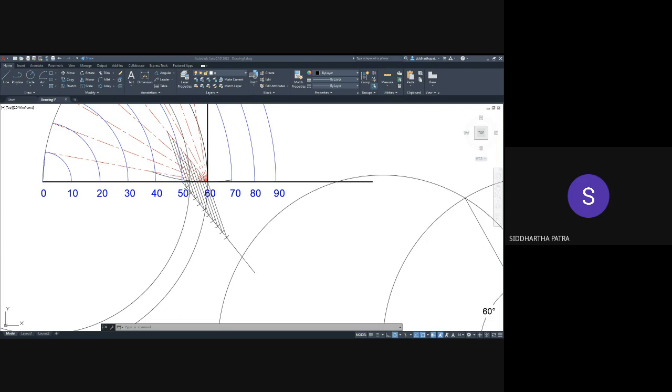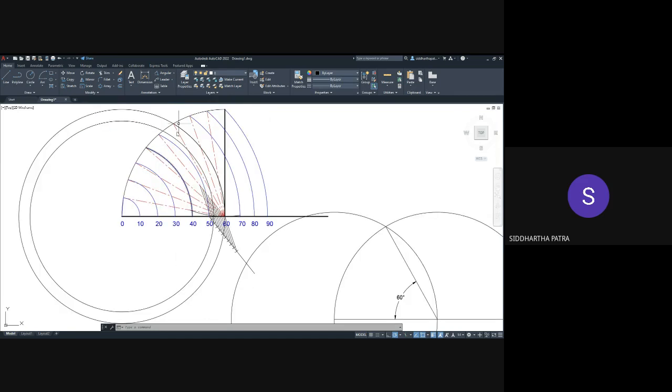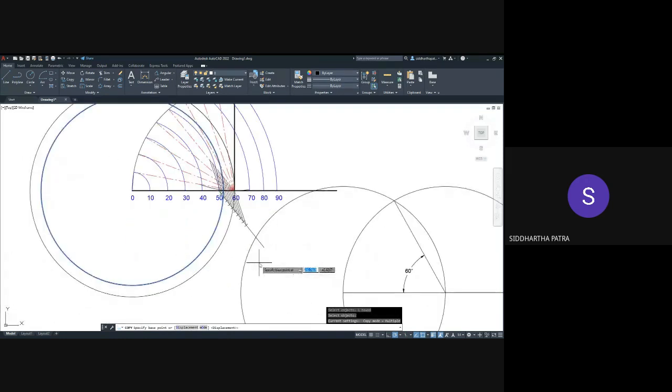Okay, so I hope you get the idea that now that I have divided the span between the chord length corresponding to 50 and 60-degree angle into 10 equal segments, I can take three of those divisions, and that could represent 53 degrees for me. But that is also an approximation, because as you can see, the gap between two consecutive degrees is continuously changing.